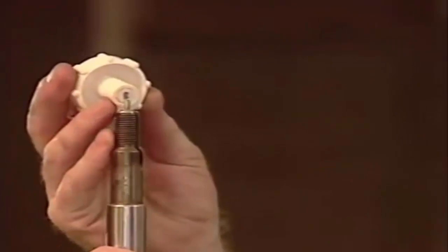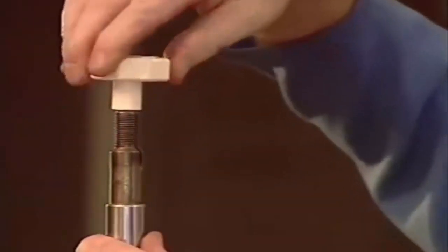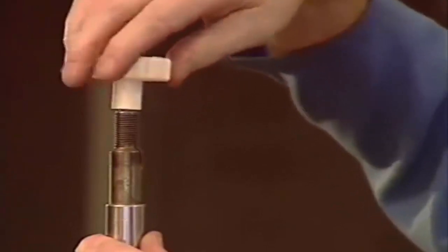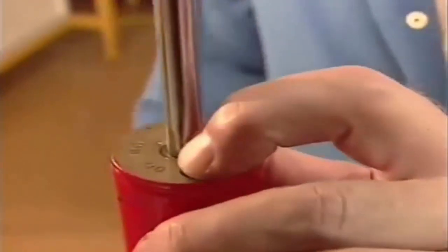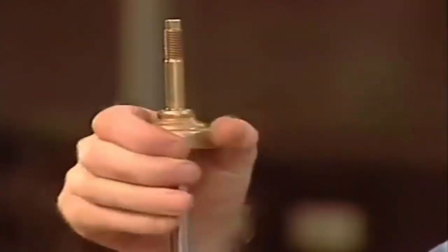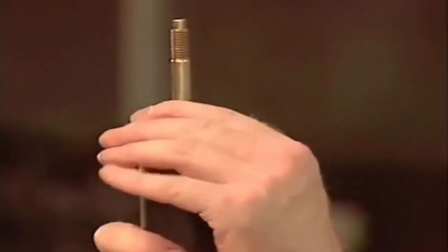The method of changing the position of the valve varies. On this model, it is adjusted by a spindle that reaches down inside the plunger. On this shock absorber, when it's extended to its maximum length, a pin is depressed, locking in an adjustable slide on the piston assembly. Twisting the two halves of the shock absorber changes the number of orifices and the spring force on the valves.